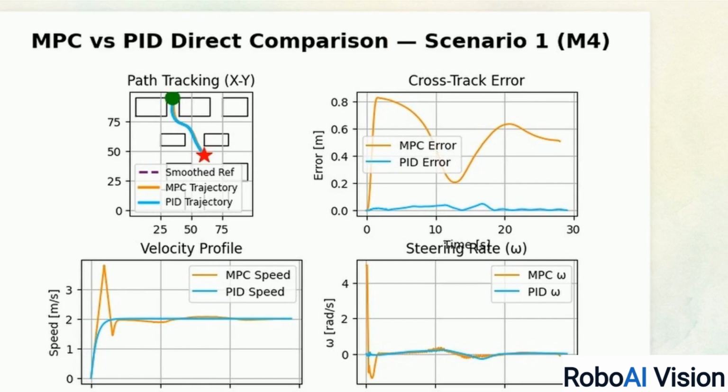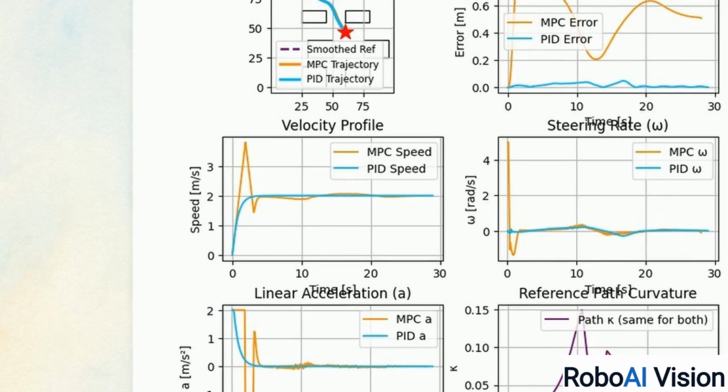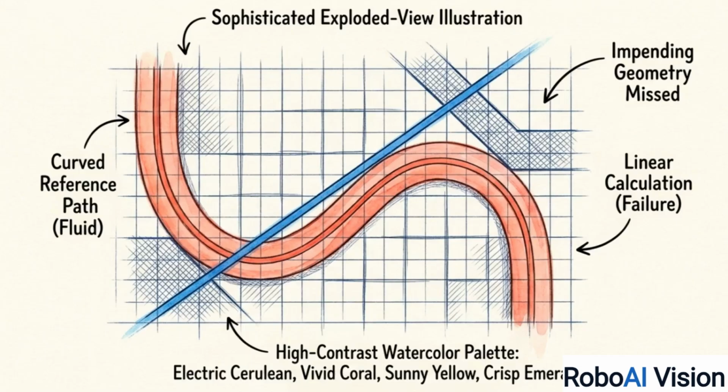The velocity profile further down reveals the exact failure. The MPC solver registers a zero mean velocity. It mathematically failed to generate a moving solution for the robot. This exposes a severe limitation. Unconstrained linear time-varying MPC assumes the physics of the robot behave linearly near the reference path.